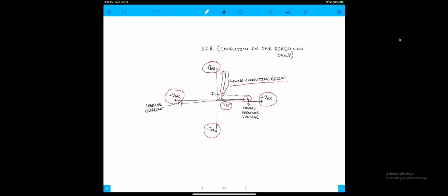While we are in this region of conducting, this is simulating that in your lab you have closed the switch, and now you've allowed enough voltage, which is 0.7 volts, to bring about the breakover and start conducting in this region.